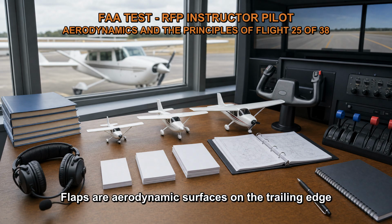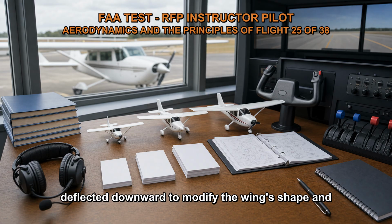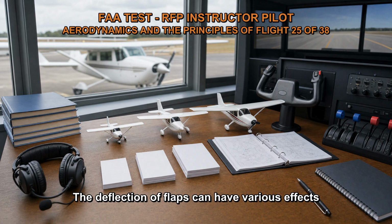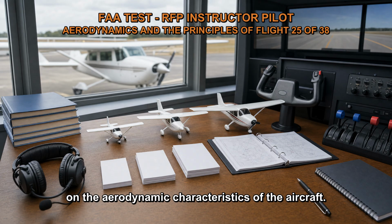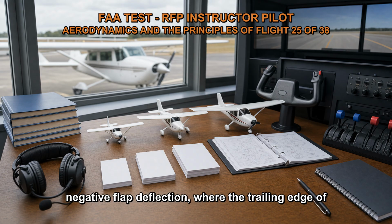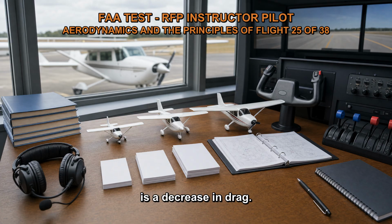Flaps are aerodynamic surfaces on the trailing edge of the wings that can be extended or deflected downward to modify the wing's shape and performance during different phases of flight. The deflection of flaps can have various effects on the aerodynamic characteristics of the aircraft. In the case of a slight upward or negative flap deflection, where the trailing edge of the flap is raised slightly, the primary effect is a decrease in drag.